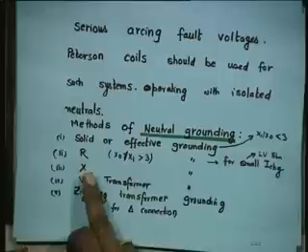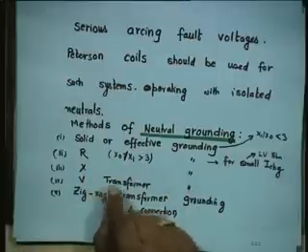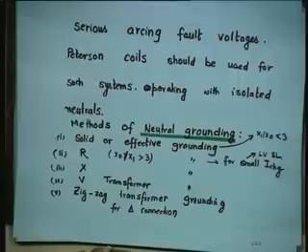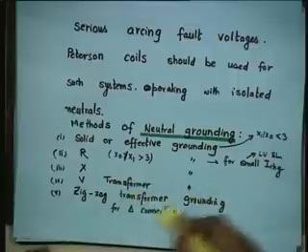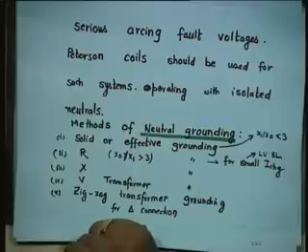Reactance you use also for grounding. We use voltage transformer for grounding. We use zigzag transformer for grounding. What is zigzag transformer? Wherever there is a delta connection, there is no neutral available as such. So, there you have to use the zigzag transformer whenever there is a delta connection. And delta connection is a practical connection. It is not a theoretical idea or a fiction.